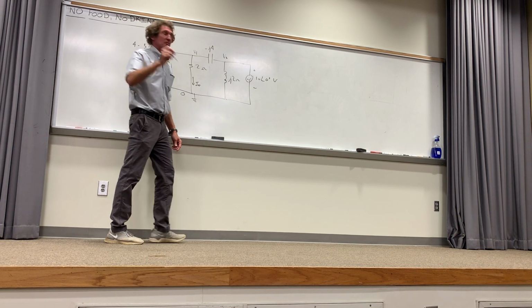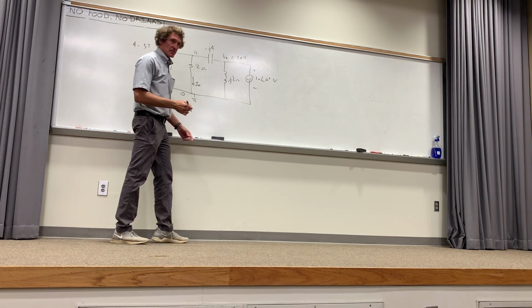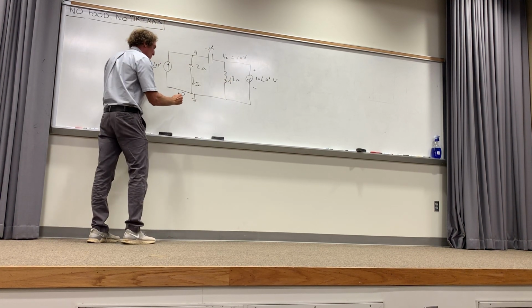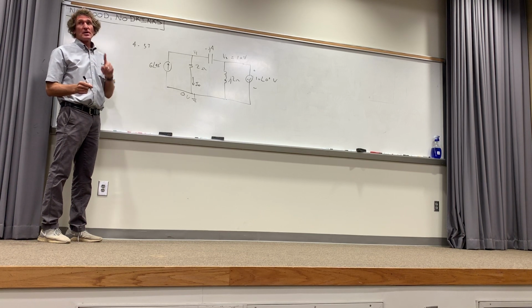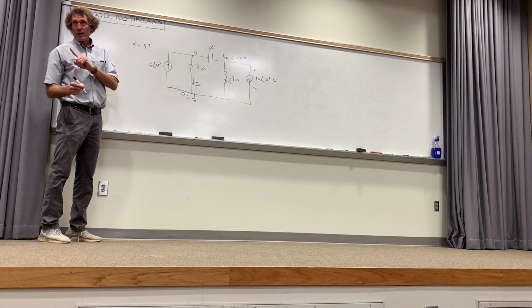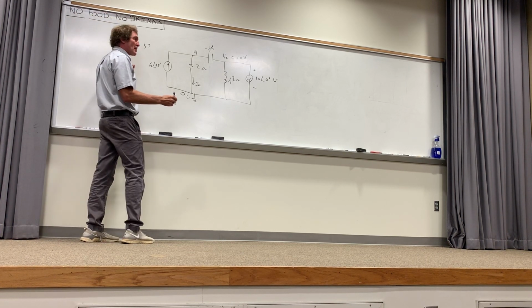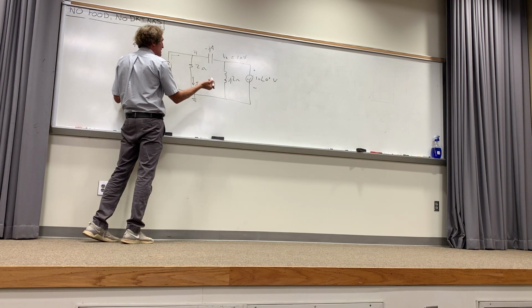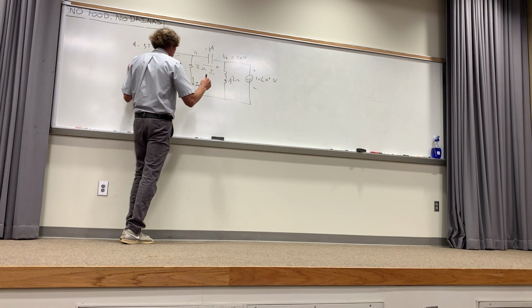There's no equation we solve. This is 10 volts. And you can forget the angle, because that's a 10 volt difference, right? It's plus to minus 10 volts. That's 10 volts above ground, and ground is 0 volts, right? Now, we're only going to need one equation for this one. So we're going to use nodal, or Kirchhoff's current law. We've already got this current. We'll call this I0, and we'll call this current just I1, all right?